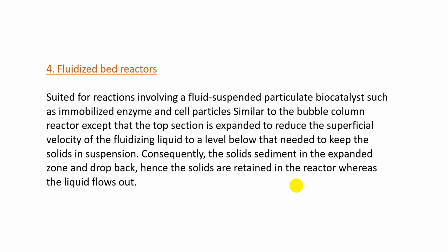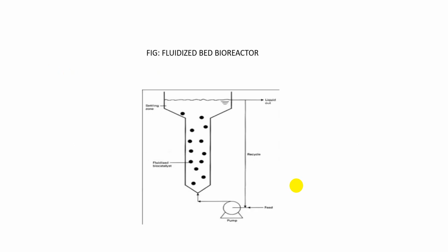Consequently, the solid sediment in the expanded zone drops back. Hence, the solids are retained in the reactor, whereas the liquid flows out. In the fluidized bed reactor, the liquid containing the product flows out through the outlet, whereas the solid support or substratum remains inside the bioreactor after the reaction is complete. This is the design of a fluidized bed bioreactor.